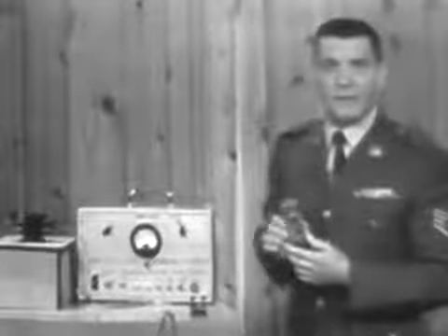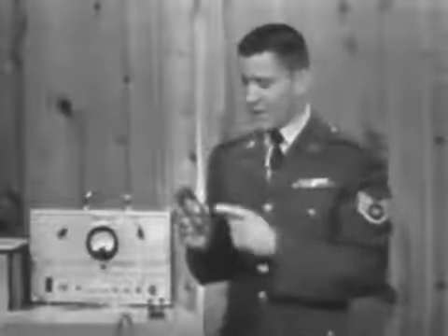Well, as a matter of fact, I've already figured it out, and approximately 70 turns of this 300 turn winding are indeed shorted. Well, we see then that for a shorted transformer winding, the ohm meter will indicate a resistance less than the normal resistance of the winding. Now, of course, the greater the number of turns shorted, the greater the decrease in the resistance of the winding.